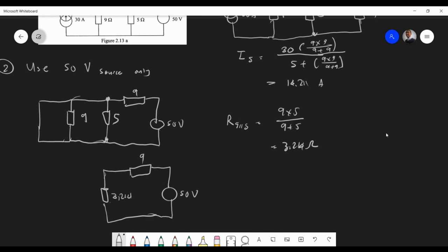So, of course, what we can do here is find, we could have also found the current if you want. It's entirely up to you the way you want to solve this. Because if you find the voltage across this new one, remember you can split it up. So it depends on the way you want to do it, honestly. So maybe we can try both just to recap. My first thing would be to find the voltage across there, use voltage division, so the voltage across that one. That's the one we want.